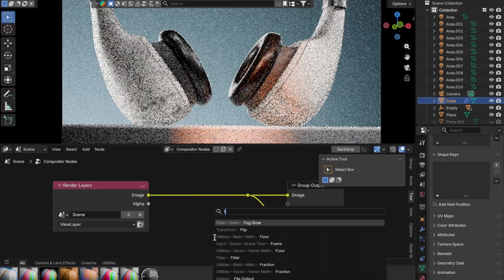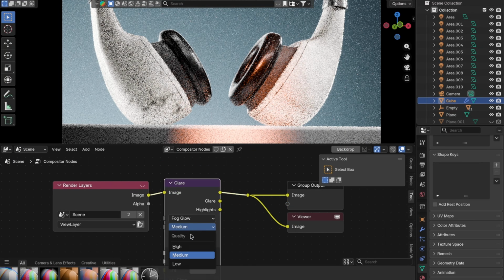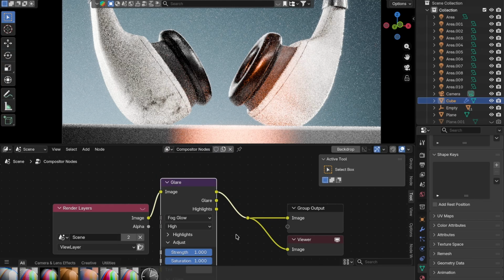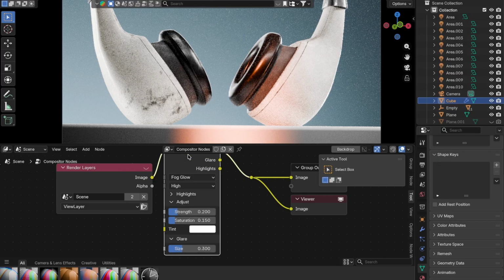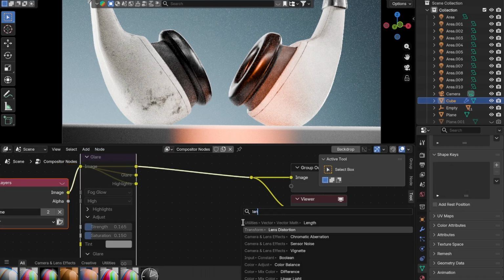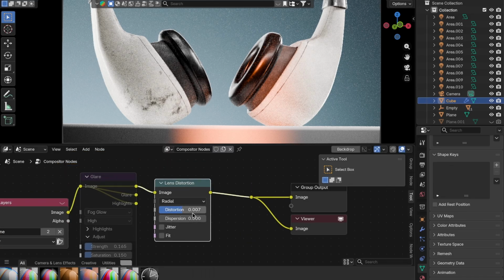I want to add the foreglow so that we have a small glow and slight haze. Just a minimal amount, with quality somewhere like 1.15, 0.50 for saturation, and let the size be 0.2. Excellent, let's compare. It's practically unnoticeable in the viewport, but nevertheless it will look pretty good in render. We don't need to overexpose it too much anyway. Yeah, let's leave it